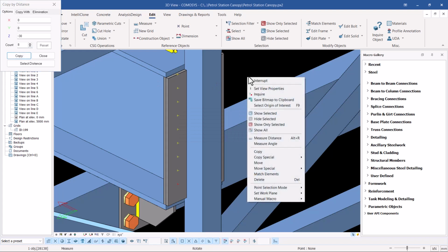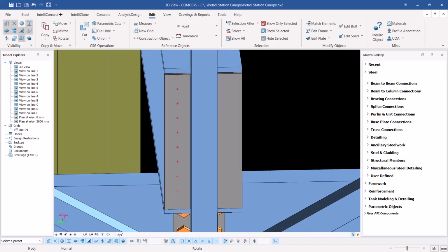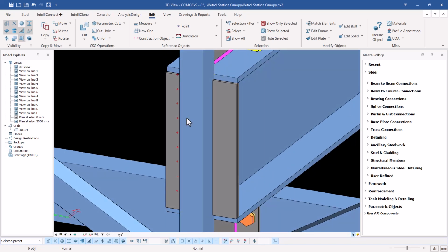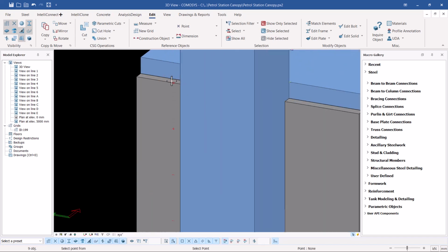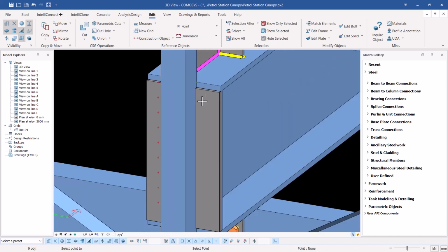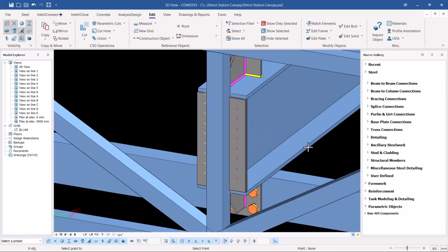So having placed the points like that, I'm going to select the points here, because we need the same points on the other end. So I'll select these points and copy them to the other end. And how do we copy them? First of all, turn this into a position where your view will not be hindered. I'm going to pick on that, snap on that spot, pick it from that spot, and place it right at the center there. So I have my points on both sides.